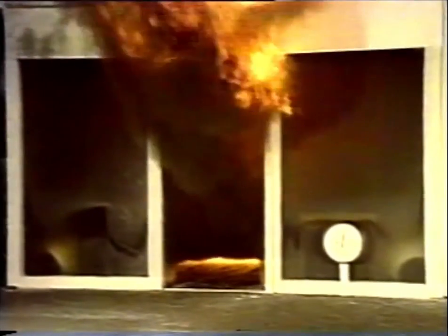If we go back to the video to a few moments after the curtain ignited, we can see that the fire is now growing significantly strong, and that signs of intense heat spread can be seen throughout the room. Also very noticeable is the thick black smoke that is now billowing out of the room. A few moments after this happens, the phenomenon known as flashover occurs. Here the remaining surfaces not yet on fire ignite almost simultaneously. The details of how and why this happens will be studied further with the use of the computational model.